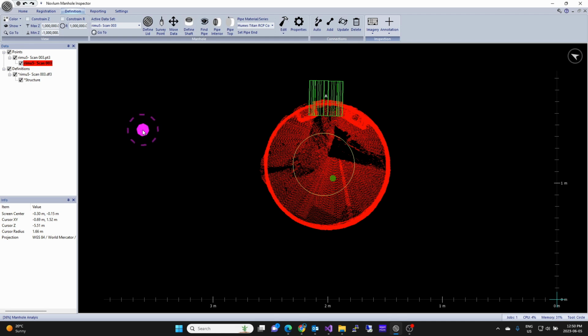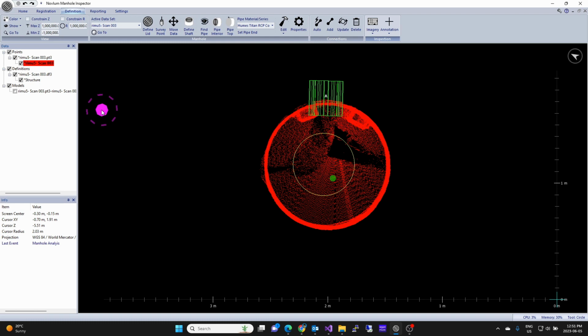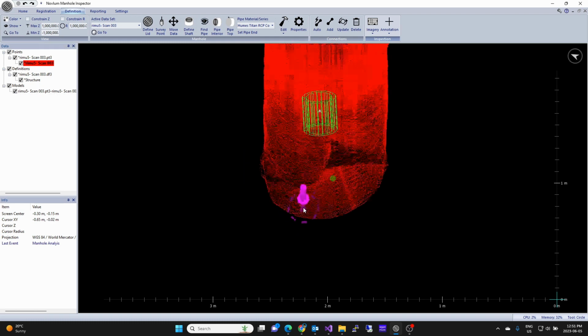The imagery is mapped to the outline of the manhole shaft that we had defined earlier. The imagery assumes the location of the scan that we picked, so the vertical location of the image will be set to that of the scan location. After importing the data, it will show up in the Contents window. We can check it off to show it overlaid on the point cloud data.